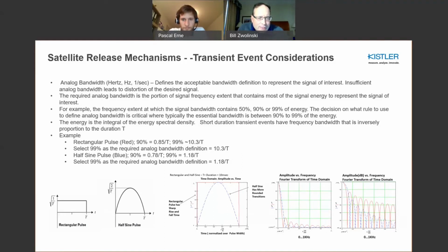We did a test recently at one company where they had an optical shutter system, and looking at the specs of the optical shutter, it was a very low level torque that we were trying to measure and very fast. And I can tell you the dynamometer had to be optimized in terms of the mounting of the test article, certainly the mounting of the dynamometer to the table and so forth, and the resolution, and it was for sure there to be able to see the event in quite high fidelity.